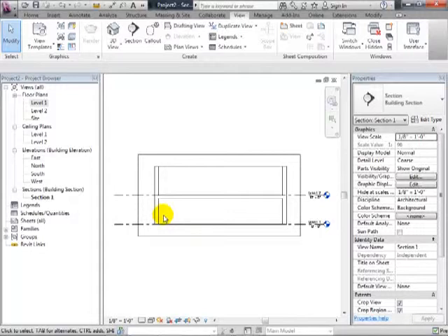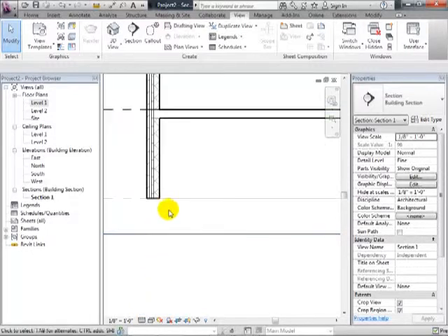If you choose it there, it's right. Just need to grab the floor and change it to level 2 right there. Okay, and then when you say apply, it will pop up. Very good. Now what happens is in the coarse level of detail, you don't really see much of the detail you want to see. However, if you go up to a finer level of detail, you actually will see it.